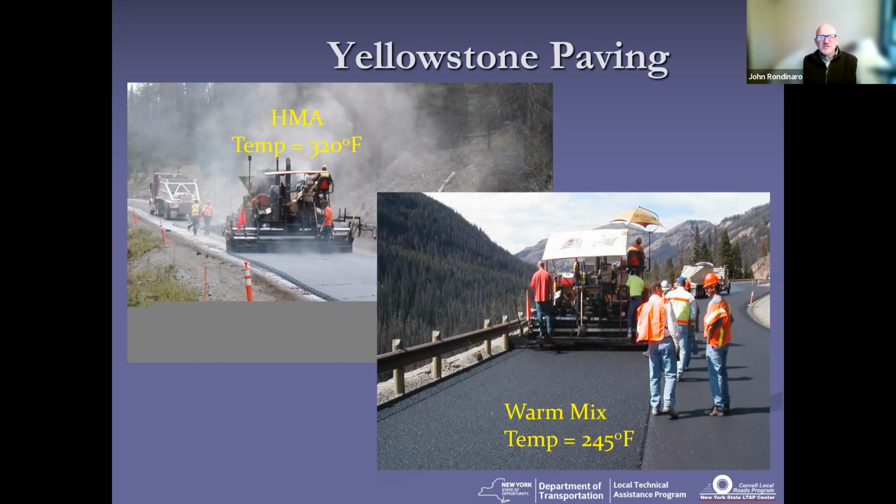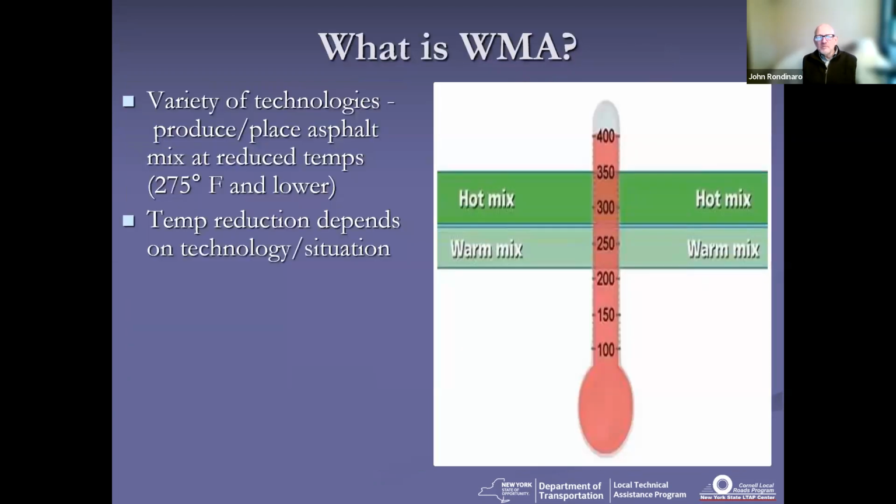And I want to take a quick second to credit our colleagues both at New York Construction Materials and at New York DOT, the Materials Bureau in Albany. They're the tip of the spear in terms of advancing warm mix as a technology. And they're the reason we've got a lot of these changes coming in 2023. And they provided a lot of the information and pictures we're using today. So again, this is just a comparison during the laydown process. And as you can see, a lot of steam coming off that mat at 320 and nothing coming off that mat at 245.